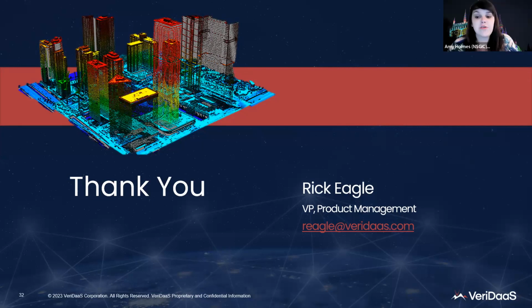Jeff asked, can you expand on LiDAR for QL1? I am aware of one project in New York that USGS purchased off the shelf from Harris. This was an existing project that was downgraded to QL1. When that was done, I believe they had a problem with ground point return, so USGS reflew the project with a more traditional sensor. This might be because it was an existing project and not initially intended for QL1.